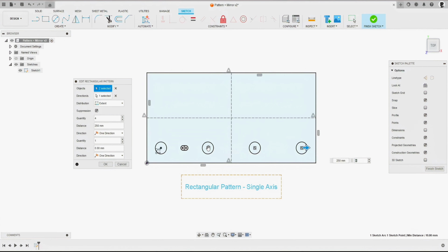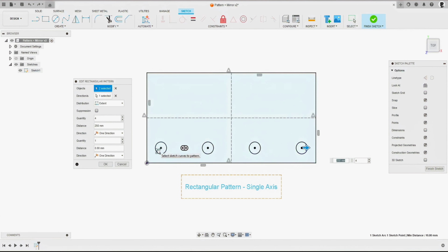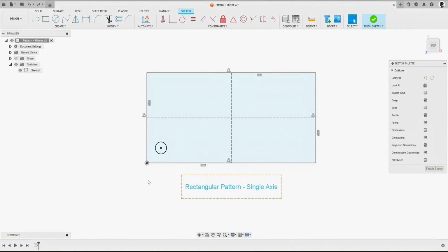And then if I select this one here, for example, and let's go for this one as well, and press OK, we can then see that those instances of our pattern are now suppressed. I press Ctrl Z on the keyboard, bring them back. Double left click on this symbol, and then we've got our toolbox available again.